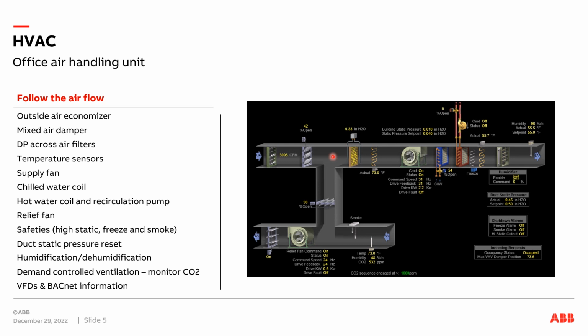Well, let's consider the situation where it's 95 degrees. We don't get a whole lot of 95-degree days in Wisconsin, but we get some. So 95 degrees, and I'm trying to cool my building. Does it take more energy to take that 95-degree air and bring it down to, say, 55-degree air for cooling? Or would I rather take, say, 75, 80-degree air and cool that down to 55? Well, it's a heck of a lot easier to cool down 80-degree air than it is to cool down 95-degree air. So on those really hot days, you bring in less outside air and you use more return air.